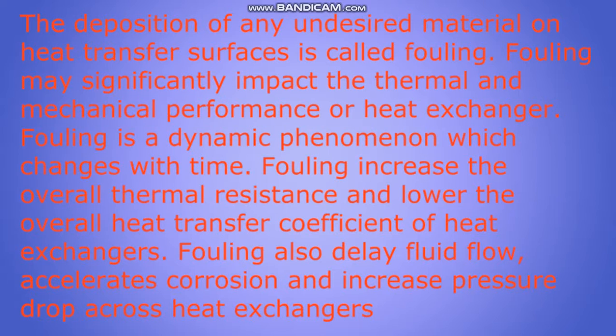The deposition of any undesired material on heat transfer surfaces is called fouling. Fouling may significantly impact the thermal and mechanical performance of a heat exchanger. Fouling is a dynamic phenomenon which changes with time. Fouling increases the overall thermal resistance and lowers the overall heat transfer coefficient of heat exchangers. Fouling also delays fluid flow, accelerates corrosion, and increases pressure drop across heat exchangers.